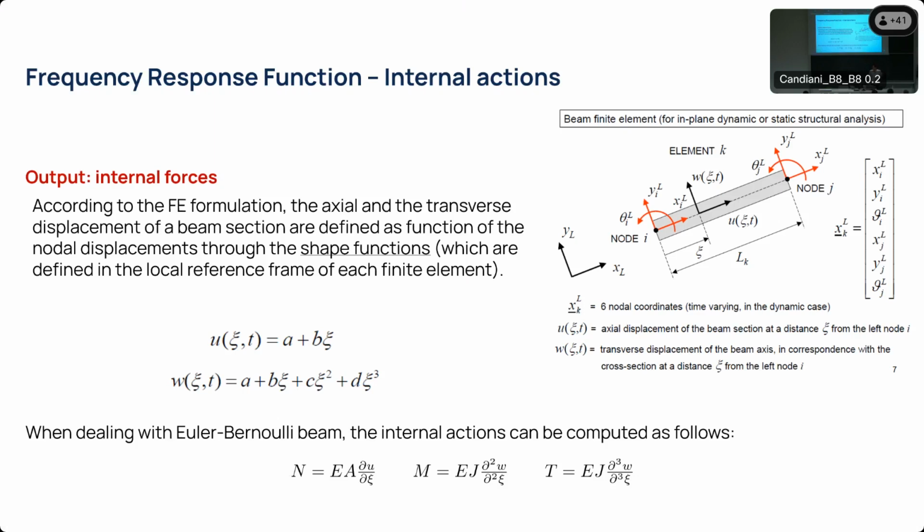So we know we can compute parameters A, B, and C, in case we want to look at the transversal displacement based on the relative position and the relative displacement of the nodes. Then we express those displacements as a product of two different vectors: the vector of the global coordinates of the neighboring nodes of the element, plus the vector of those coefficients evaluated at different values of parameter xi, and then we are able to get a vector of horizontal and vertical displacement of our element.